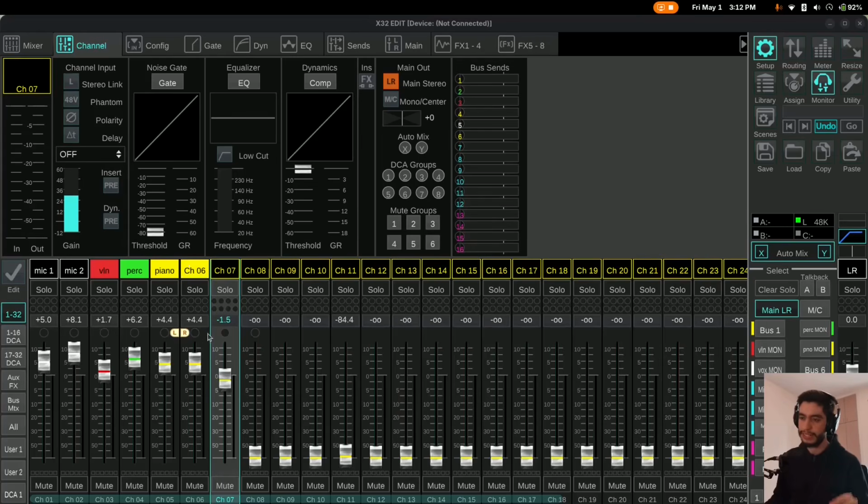If you turn down the speakers to an appropriate level like I just described earlier in the video, you can turn up the fader all the way to plus 10 and not worry about anything and leave it there, and it wouldn't feedback. Which brings me to my next point. With speaking mics, that's what I said in the beginning of the video, even if you turn it up all the way up, you might still feel like it's a little bit quiet.